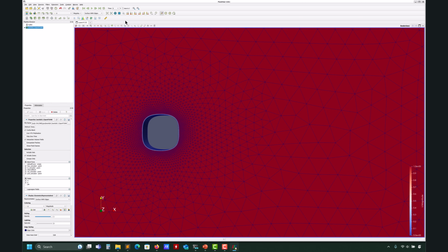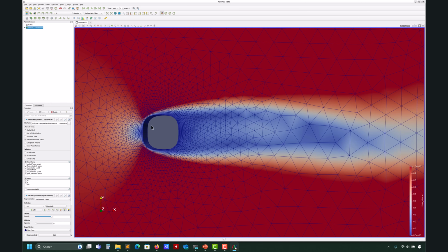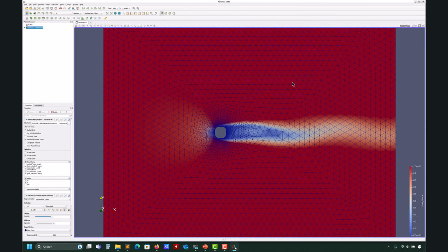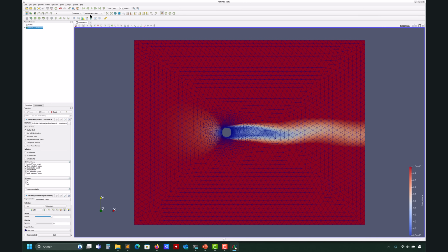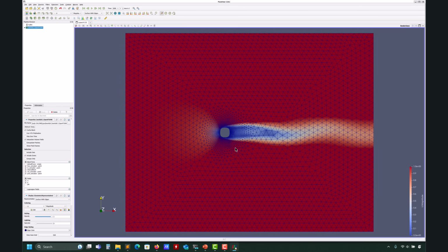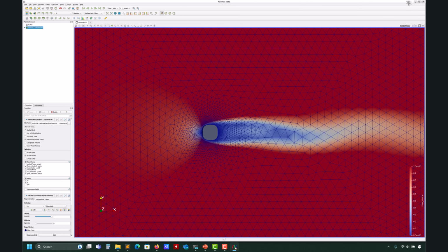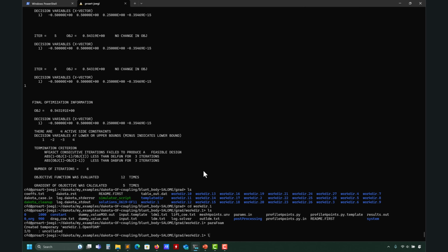And here you have the starting point, and this is the solution that we have. You see that we have an unsteady flow, the way it is oscillating, so that can make things a little bit tricky in optimization. We already talked about that when we addressed the foundations: optimization, when it's unsteady, is not easy. When you have this case, look at your average solution, don't look at the instantaneous value, because for every single value you are going to have a different optimal value. So you want a global quantity. This will be the case.